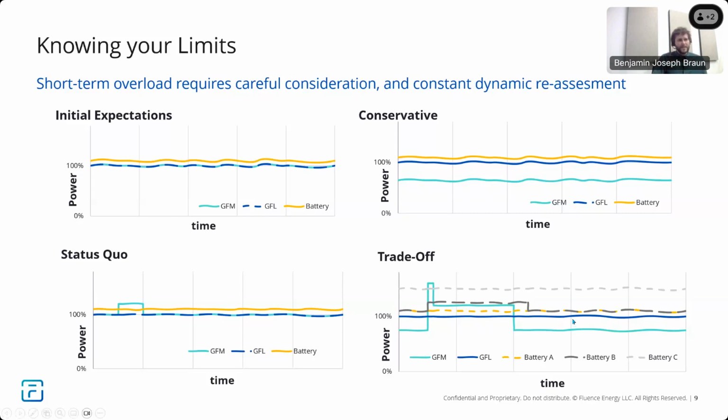And then you have the more complex, but potentially the more beneficial, a bit of a trade-off, where they say, right, if you give me a bit of headroom on your plant sizing, so effectively derating your PCS, your inverters, or overbuilding them to derate them, when you actually need the short circuit current, or the overpower for inertia, I can give you so much more than if you wouldn't have overbuilt me.